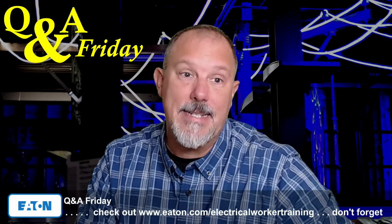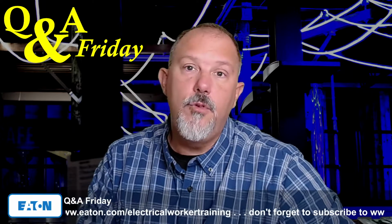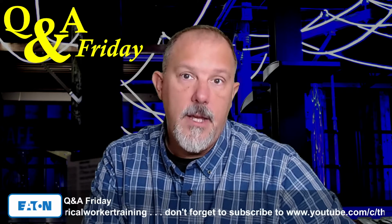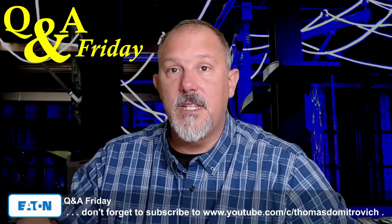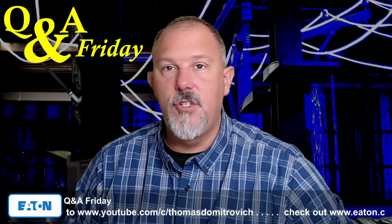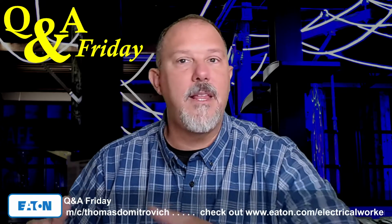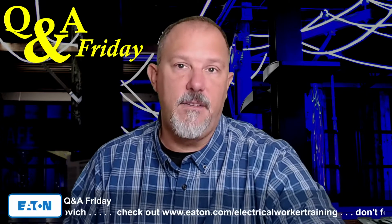So that correlating committee task group is working to, for example, I'm chairing a medium voltage task group for 210 because we accepted the creation of a 231, and we are moving the medium voltage requirements out of 210 and moving them into 231 so that the requirements that we create in Article 231 apply to medium voltage and only medium voltage. So you don't have duplication in 210 and in 231, and we're making them stand alone so that you don't have to keep referencing back and forth.